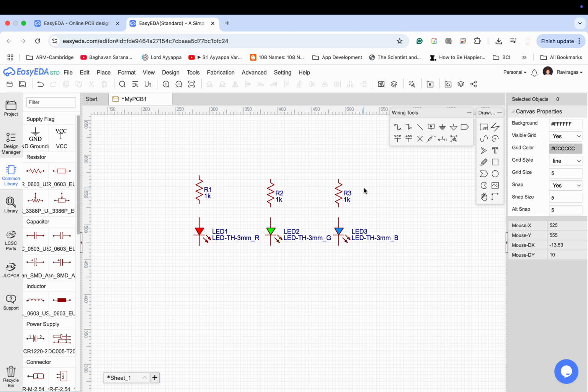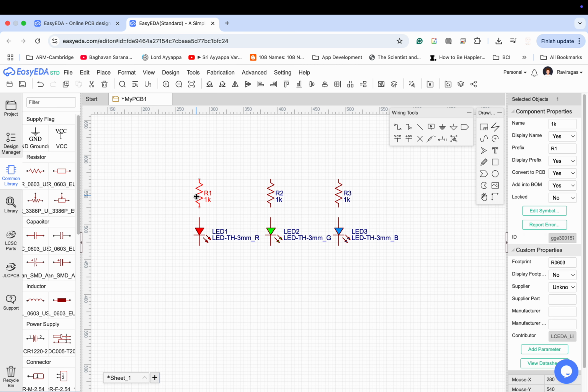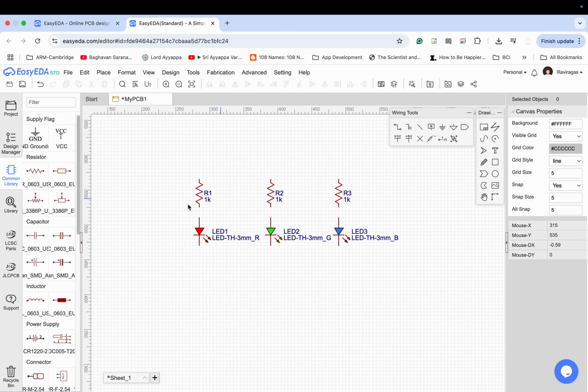Again, it's up to you whether you really want to buy a Molex connector set, or you can just use the pads and wire and solder 2 wires. It will still work the same way. So let's go ahead and put the connector.